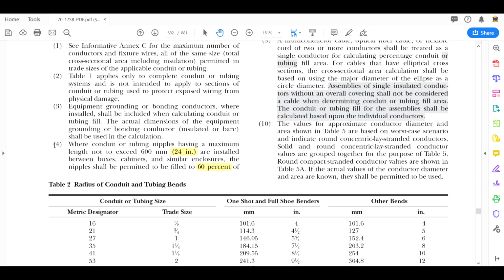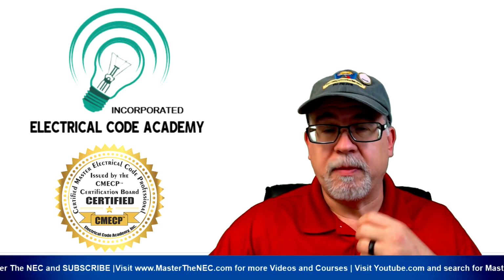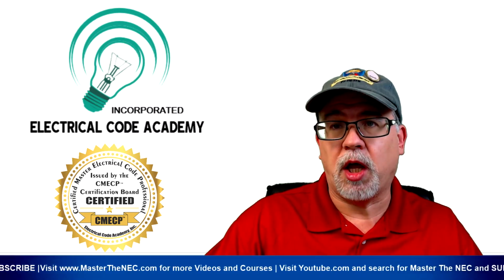The next one is note number 4. This is when we're dealing with those nipples. This is conduit or tubing with a maximum length not exceeding 24 inches, and it also requires that it is installed between boxes, cabinets, and similar enclosures. So that's what the nipple is. This allows me to fill it all the way up to 60%. So up until this point, we were talking 53, 31, 40.